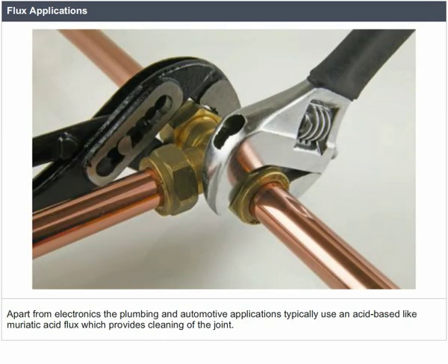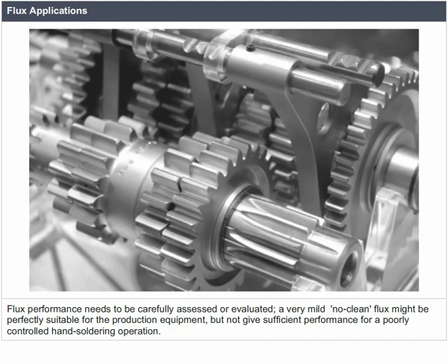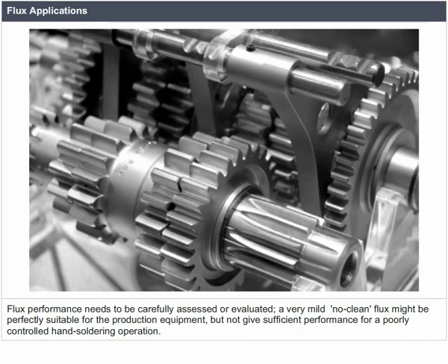Apart from electronics, plumbing and automotive applications typically use an acid base like muriatic acid flux, which provides cleaning of the joint. Flux performance needs to be carefully assessed or evaluated. A very mild, no-clean flux might be perfectly suitable for production equipment, but not give sufficient performance for a poorly controlled hand soldering operation.